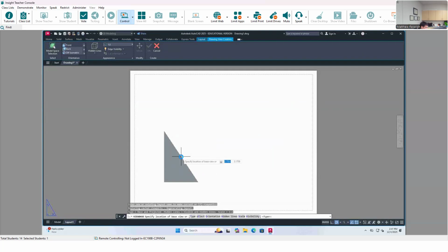And yes, we can manipulate it. It's always better to pre-plan ahead and get it correct, but it is manipulatable at this level too. The long story short, it's going to want to drop what we call a parent view, the front view. It's pretty standard, right? We've just drawn that way ourselves as drafters anyway. It's our really important view, good details, most stability, all the jazz of a front view.